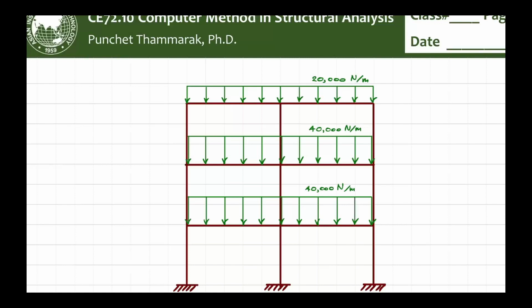So it traps the water, and if your concrete is porous, water seeps down, then it comes to meet the steel reinforcement. Steel reinforcement gets rusted. Maybe for the first few years the carbonation is not there yet, so the pH is still very high, so it is difficult for corrosion. But as the structure ages, it is exposed to carbon dioxide, and then you have carbonation penetration. So the pH drops. Steel reinforcement gets corroded. When the rust comes in, it expands.